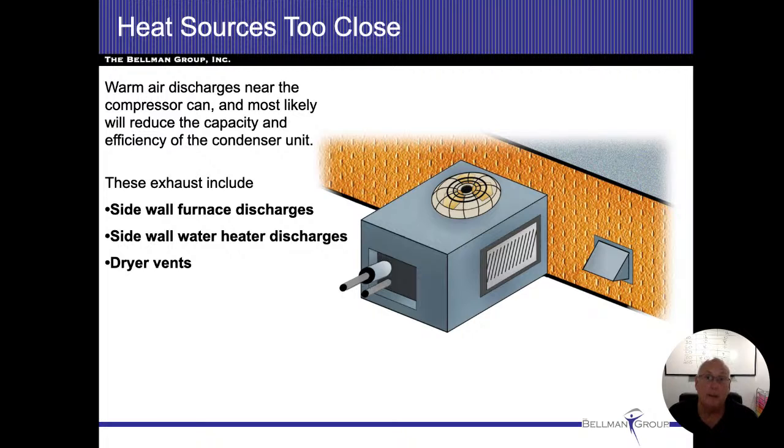However, the condensation that comes off of a sidewall vented furnace, because it is a condensing furnace, that condensation is very caustic. And if that gets blown onto the fins on a regular basis in the winter, we're going to start rotting and deteriorating those fins like there's no tomorrow. All right, so that in itself, I think, is a big deal. And yeah, the air shouldn't be blowing on the fins.